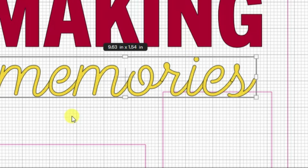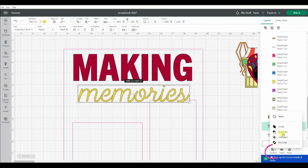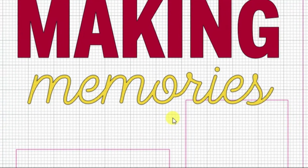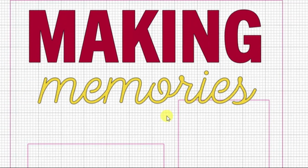So if I were to click make it right now, this would cut the E separate from the S. But I want it to cut all one word. So I'm going to use combine and weld. You can see what that did is remove the cut lines between things. So use weld when you want to remove the cut lines between different elements.